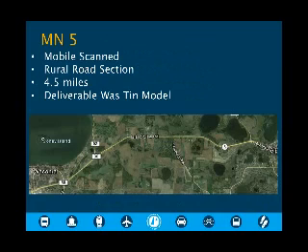Wave 5 we just did this past summer. There was no existing profile on this road. It's kind of rural out on the west side of the metro. We had nothing in any of our old plans that showed a profile, so the designer needed to come up with it because they were adding turn lanes, they were changing grades, and they knew there were some sight distance things that they wanted to fix, those kinds of things.